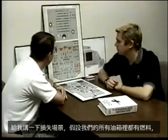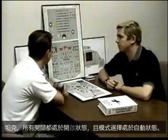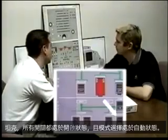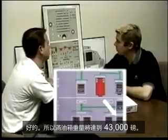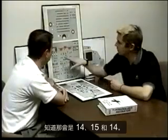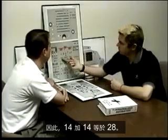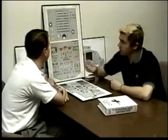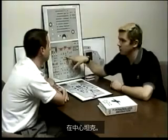Walk me through a loft scenario in which we have fuel in all the tanks, all the switches are in, and the mode select is in auto. Okay. Starting with pushback, full tanks is going to be 43,000 pounds. And we know that that's going to be 14, 15, and 14. So with 14 and 14, that's 28. Anytime I have more than 28,000 pounds, I'm going to have fuel in the center tanks.